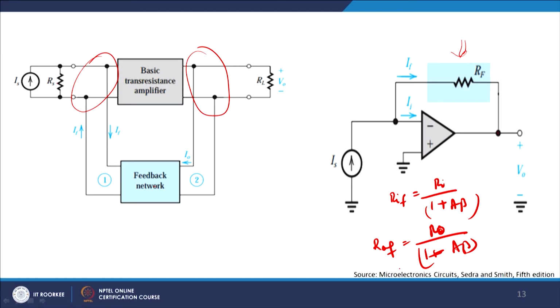So, one thing you should always remember is that in presence of shunt the impedances fall down, in series the impedances rise up. Shunt-series and series-shunt, series will rise up, shunt will fall down, and in all the 4 cases your gain will always drop down if you have a negative feedback. So, this is a common thread across all the amplifiers which you see.